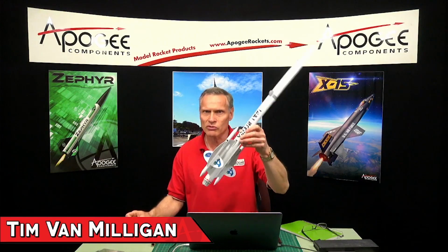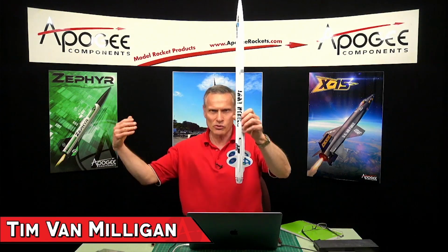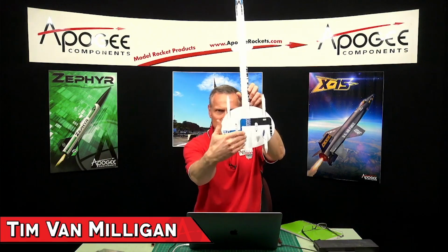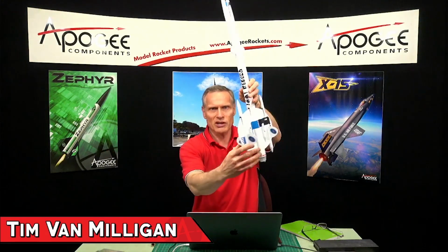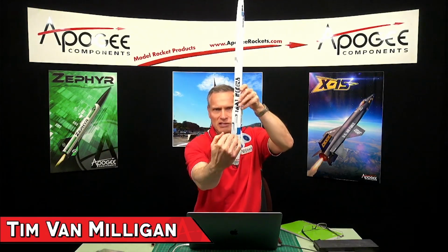And how does RockSim handle that? And how do you know if the rocket's going to fly straight when you launch it? Because on an asymmetric rocket, the direction that the wind hits it makes a difference. If it hits it this way against these big fins, it's going to cause it to rotate this way. But if you're sideways on it and the wind's coming from that same direction, there's less fin area to cause rotation. So the direction of the wind is important on an asymmetric rocket, and that's what we're going to talk about.